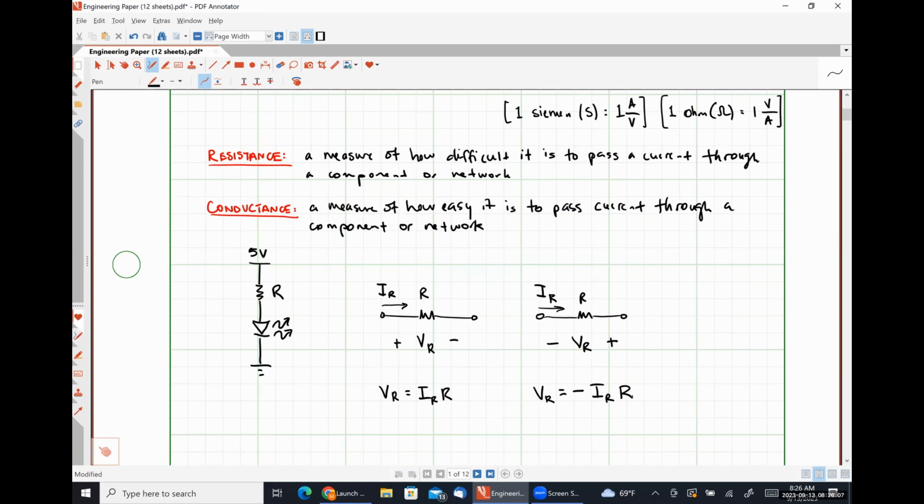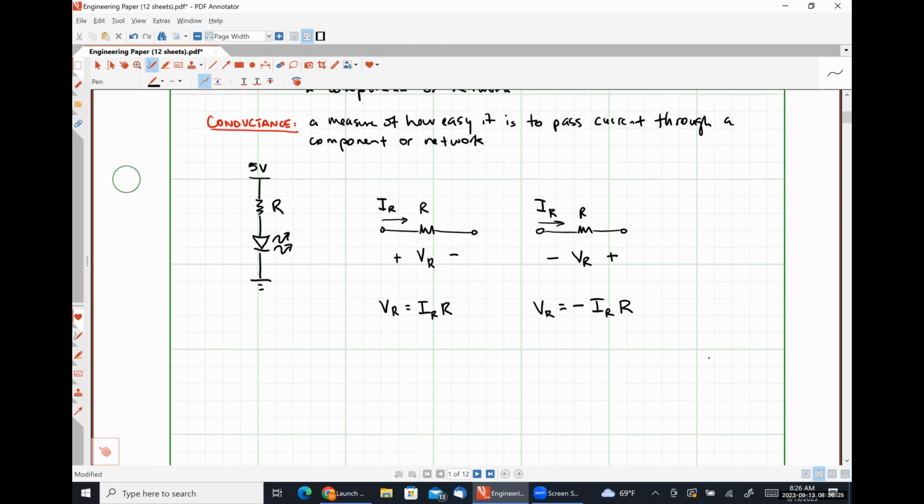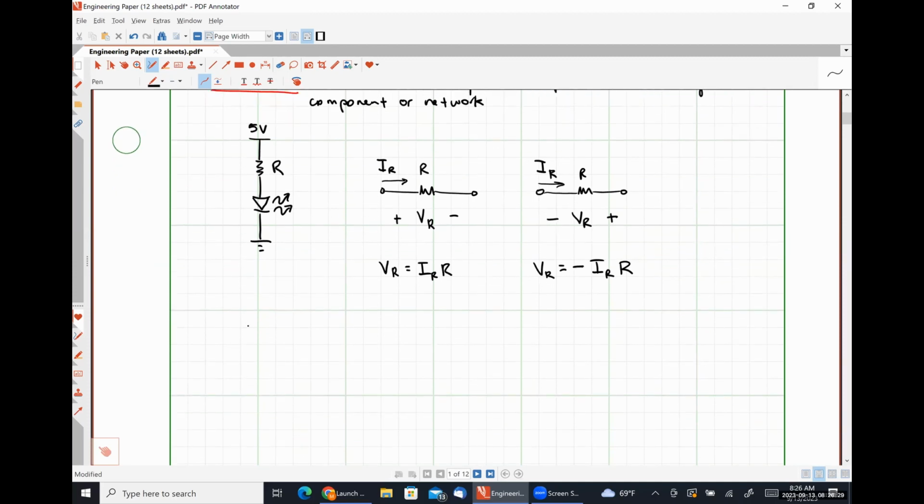Okay. So Walker just a moment ago mentioned the concept of a short circuit. So let's talk a little bit about that by exploring the relationship between the geometry of a conductor and the resistance of a conductor. Okay. So this is something that I believe, at least back when I taught the Engineering 120 series, this is a relationship that you guys were taught, where resistance is equal to rho E times L divided by A, where rho E is the electrical resistivity.